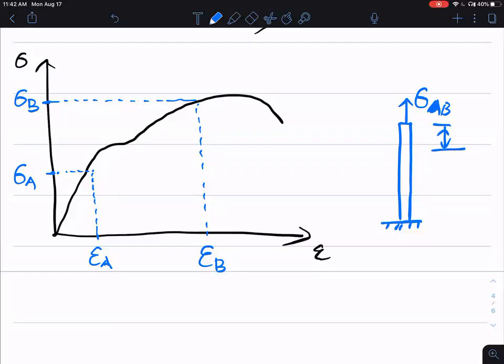So it's kind of like a spring. You guys all played with a spring when you were a kid? You stretch it, you release it, it goes back. But sometimes you broke it. What happens? You stretch too much and you release it. It goes back a little bit, but it can't go back to its original shape and size anymore, right? So it's a kind of combination of both elastic deformation and plastic deformation. Same deal happens here.